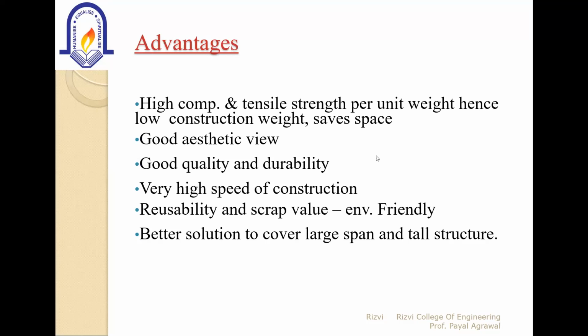As you know, for the reinforced concrete, if the structure is made up of RCC, that is reinforced cement concrete, its scrap value is nothing. The scrap value is almost zero, that is almost negligible. But if the structure is made up of steel, you can reuse it, and also it is environmentally friendly, and the scrap value is also good if you use steel as a construction material, as well as a better solution to cover large span and tall structures.